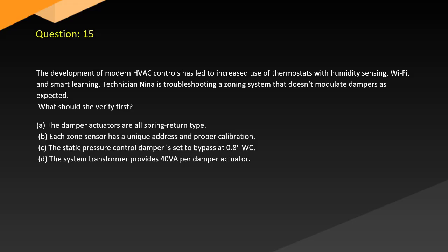A. The damper actuators are all spring return type. B. Each zone sensor has a unique address and proper calibration. C. The static pressure control damper is set to bypass at 0.8. D. The system transformer provides 40 VA per damper actuator.